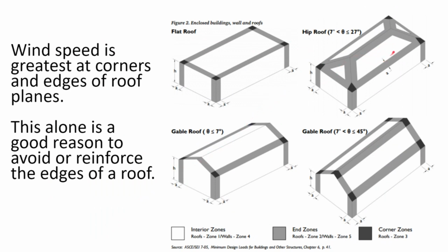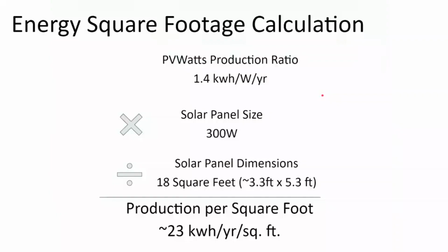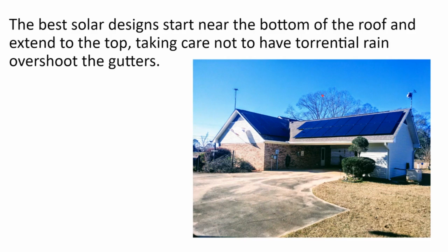That extra space is useful for solar array maintenance, so there are many reasons not to put the solar array all the way to the sides or top of the rooftop. The bottom edge of the roof is a different case. I don't want workers anywhere near the edge of the rooftop, so by filling the bottom region of the roof up with solar, I might physically prevent a worker from walking along the edge of the roof.